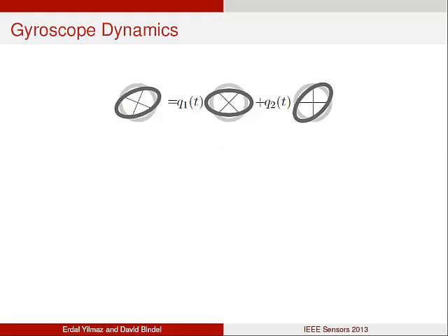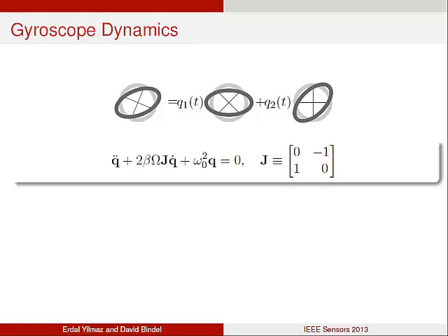So what's a solid-wave gyroscope? An axisymmetric body supports pairs of vibration modes which have the same frequencies. And a simple vibration of the device can be written as a linear combination of these two mode shapes. The time-dependent coefficients q1 and q2 here are like the coordinates of motion. And the equation of motion for this system is governed by this 2x2 lumped model.